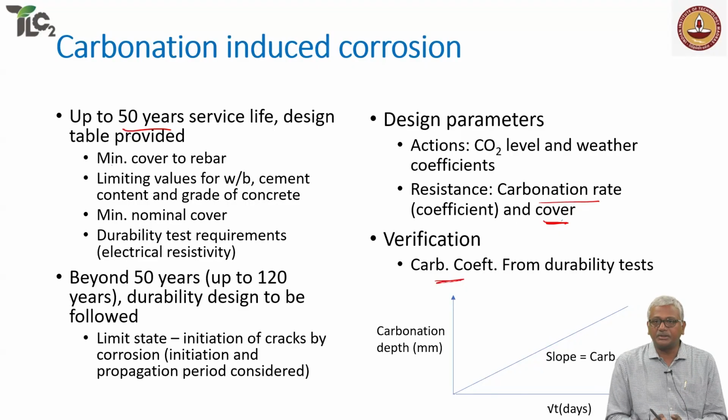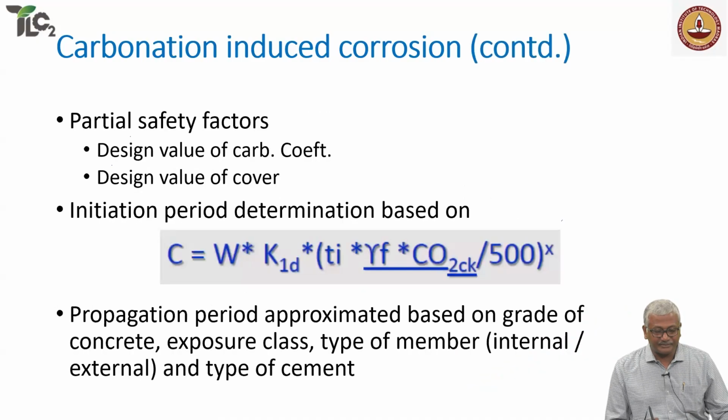Concrete structure which has a design life of more than 50 years, we need to start now following the steps of durability design. This is needed or mandated in the new IS 456, and again a partial safety factor definition is also given for carbonation coefficient values, cover values, and so on. And the initiation period is defined based on this equation, which is essentially just a typical variation that we see in terms of the weather, in terms of carbon dioxide concentration, and so on. And there is also a propagation period given.